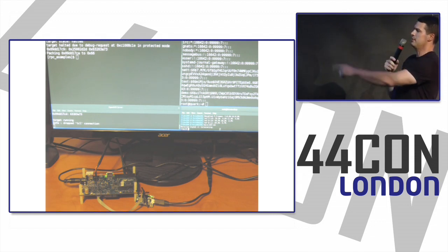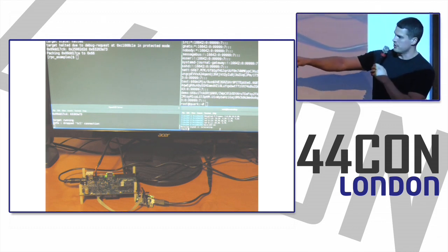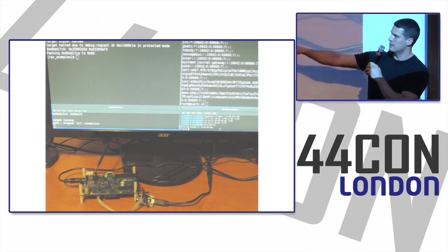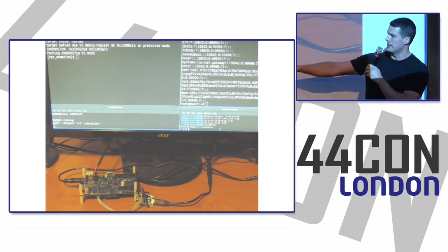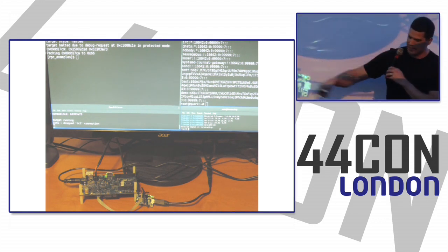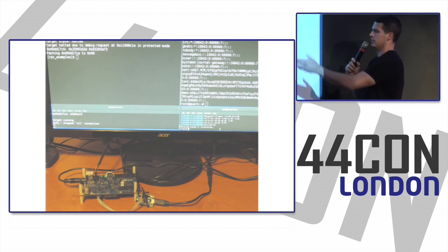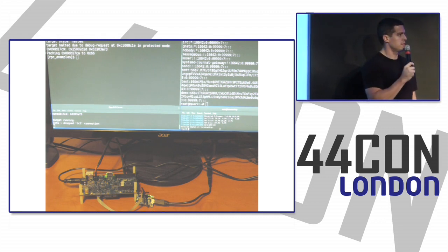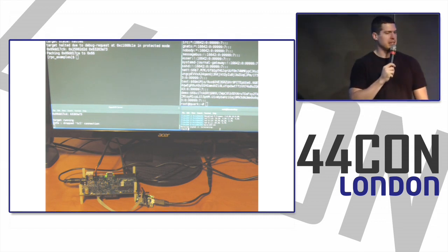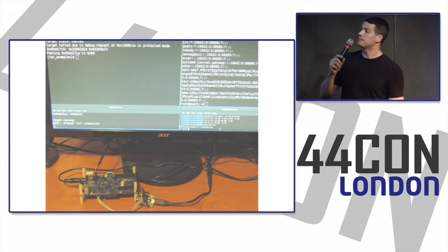So I was going to say, this is pretty much the same target setup we had before. The Galileo, which is the target system. I've got the serial cable to log into it, and then the USB. This ribbon cable right here is actually the JTAG wires going over to the Galileo, and then it's just an Adafruit FT232H based JTAG adapter running back to my desktop.